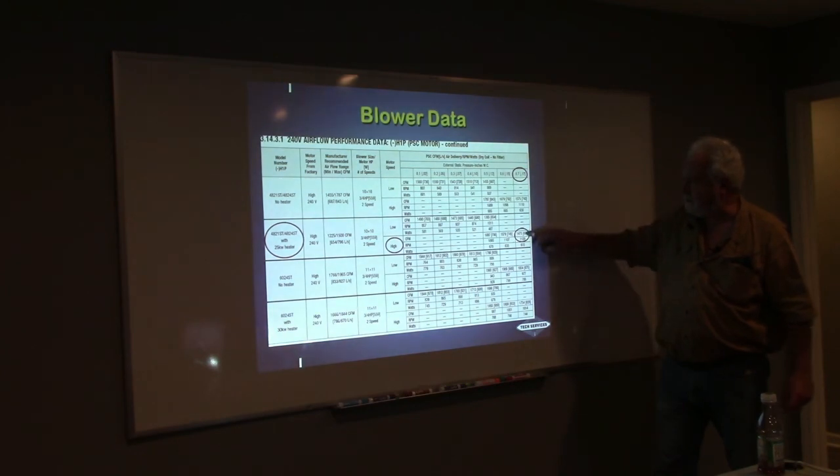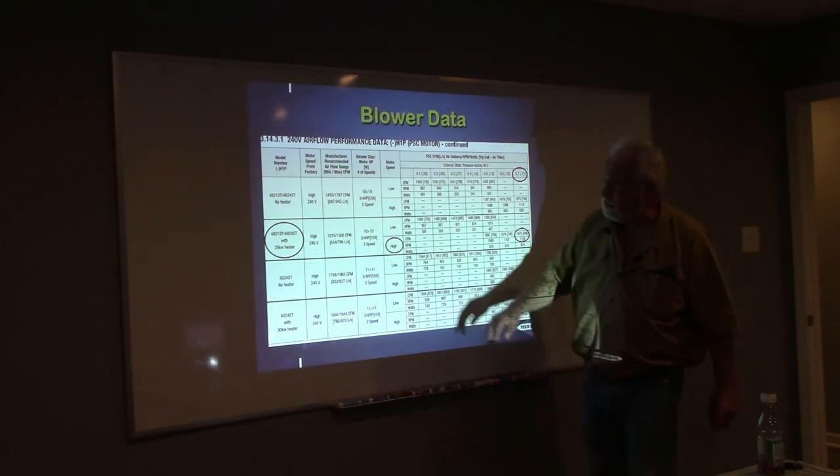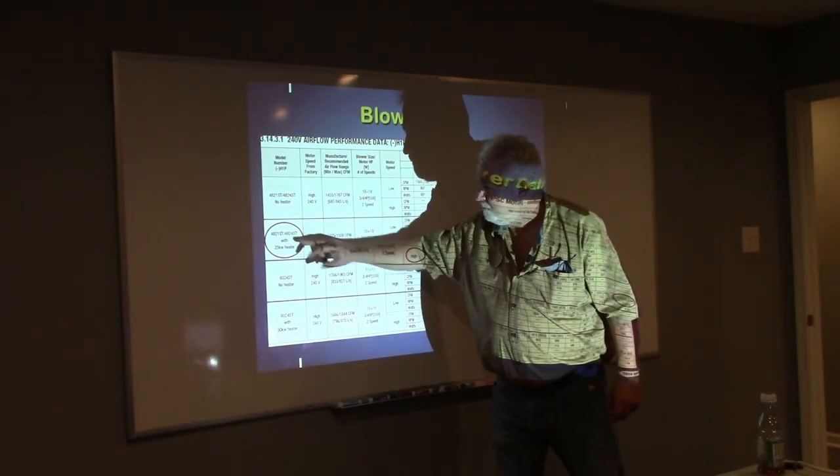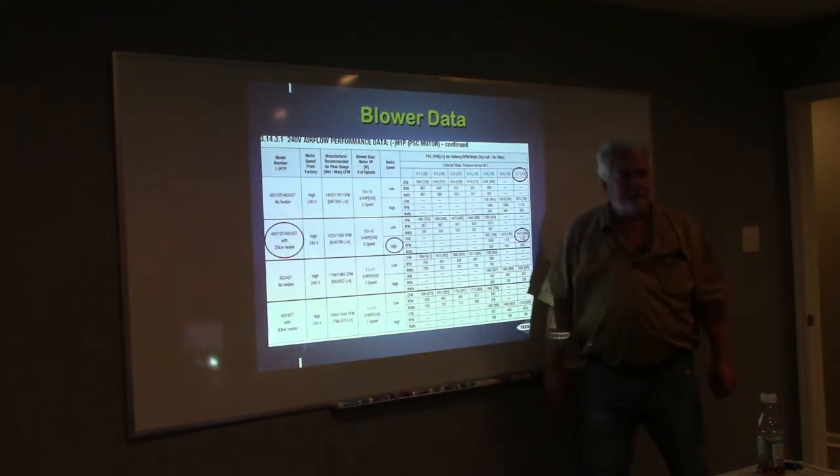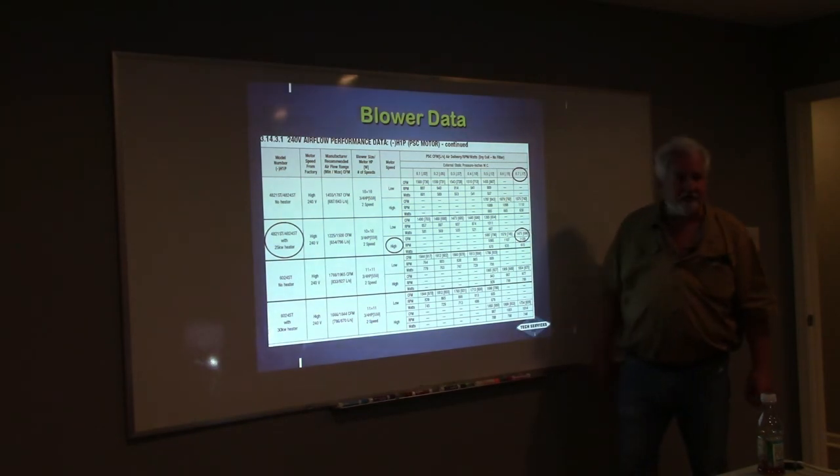The CFM is 1475. This may not do very well at all because this is a 4 ton, a 4 ton with 1400 CFM. And look at where it's at on the chart. You see the chart go any farther? What does that mean? We're already at the high end of this thing, right? Good. Where's our problem? You've already discussed where our problem was.